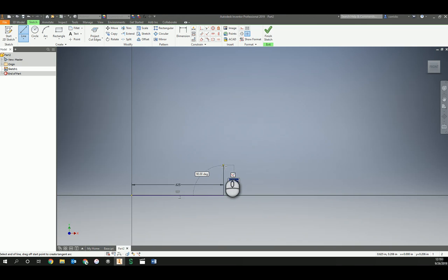and I wanted it to be 0.25 up, a 1/4 inch. And then I'm going to make a square here, 0.125. And then I'm going to come up and do it again, 0.125. I'm going to come over. Now this one is automatically recognizing that I want it to be 0.125 since I already have a dimension there. So I'm not going to dimension it again. Then I'm going to come back up. Now in this case I do need a dimension, 0.125. Enter that again.